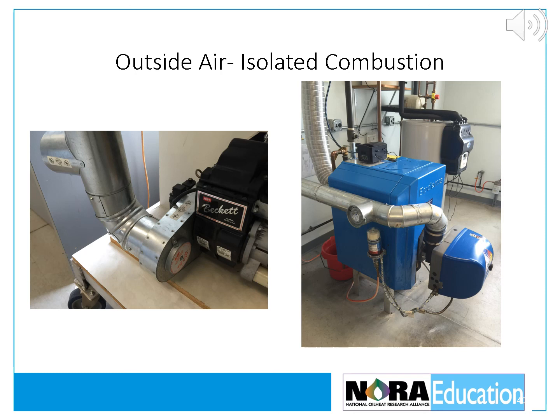Air infiltration loss is greatest for heating appliances that operate with large quantities of excess combustion air or units that have large off-cycle air flows. Efficient units will operate with low air infiltration losses. The best solution for air infiltration loss is isolated combustion, whereby outdoor air is piped directly to the burner air intake. Infiltration losses from new units with isolated combustion air that require no draft regulator can be almost zero.